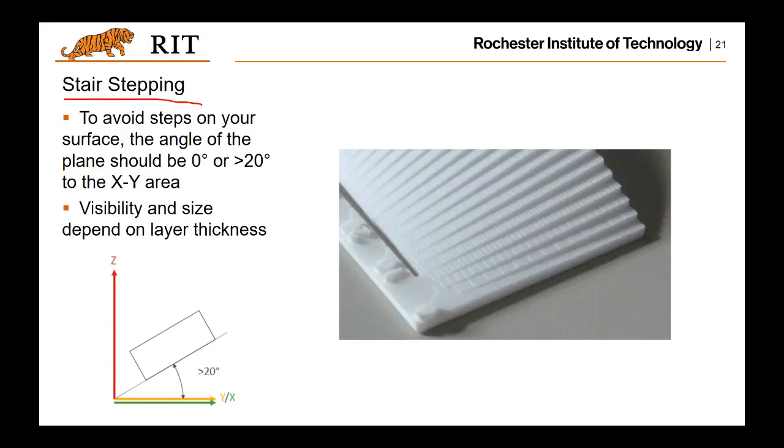So similar to other additive manufacturing processes, there will be a stair-stepping effect because of the layer-by-layer manner of the printing. But to minimize this stair-stepping, you want to make sure the angle of the plane to the XY plane is either 0 or larger than 20 degrees.